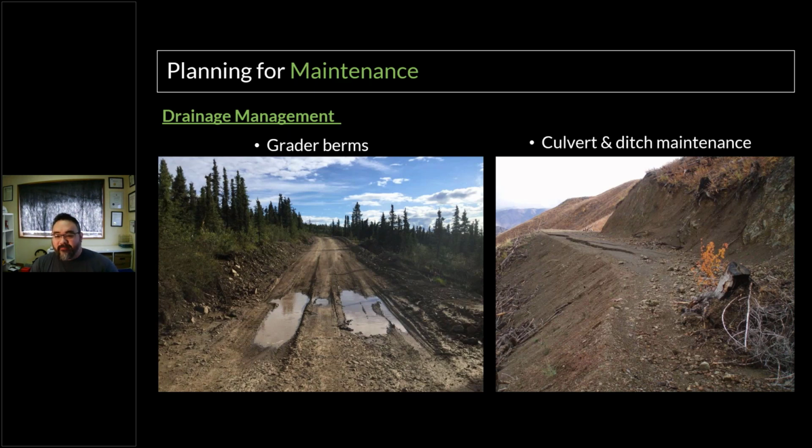time. But don't let grading be that secondary activity. Oh, Joe's got nothing to do today, send him on the grader and scrape the road off. And Joe will literally go and scrape the road off. He'll scrape the surfacing into the ditches, he'll scrape it flat, and maybe fill a ditch. On the other side there, we have what happens when we don't maintain our ditches and culverts. We can concentrate flows onto fill slopes.